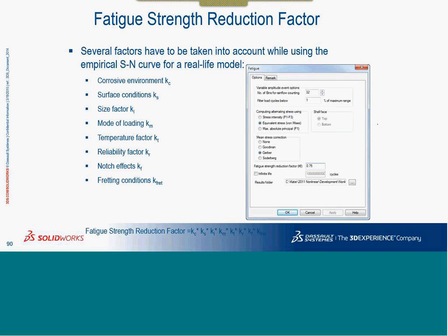Now we are discussing obviously cycle fatigue, which is not because of localized cracks, but more of material deterioration over a period of time, and we are comparing with SN curves to get it. But even the SN curves are typically derived from a standard specimen. So the specimen has a good surface finish, it has a certain amount of corrosion or zero corrosion, the size is decided.